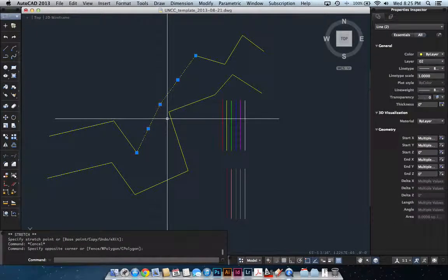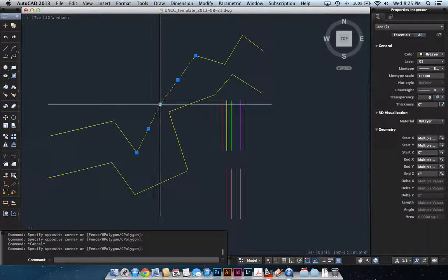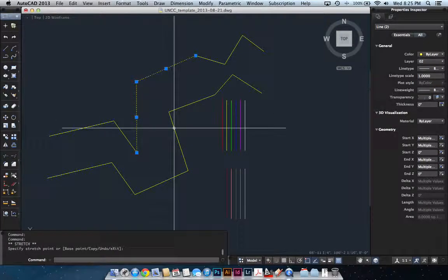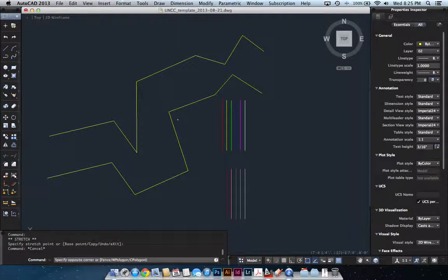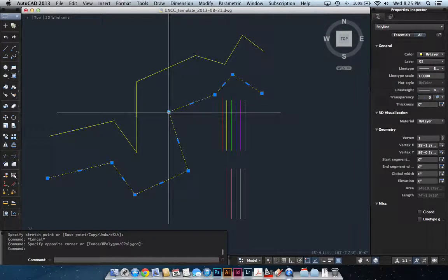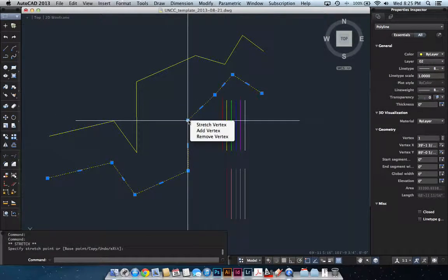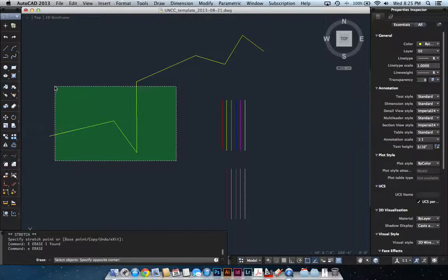I can of course grab lines together, again with this pick box that goes from bottom right to upper left. This selects anything it intersects, regardless if it intersects the entire object or just a portion of it. And now I can distort that, but I had to select that as two separate things. So again, if I just go back here and grab the polyline, it gives me the entire thing active with one selection, one element selected. So I'm just going to erase those, go back,